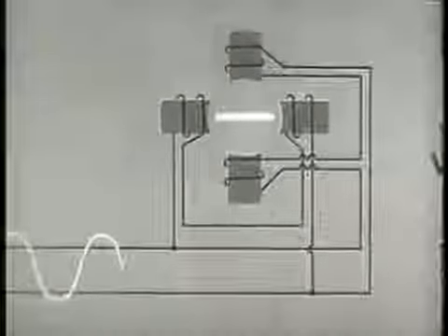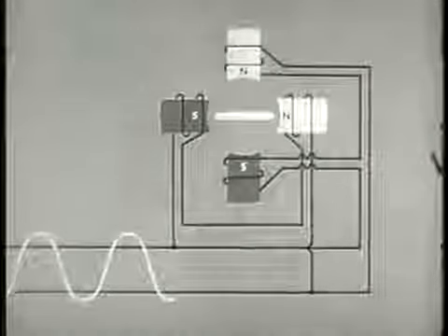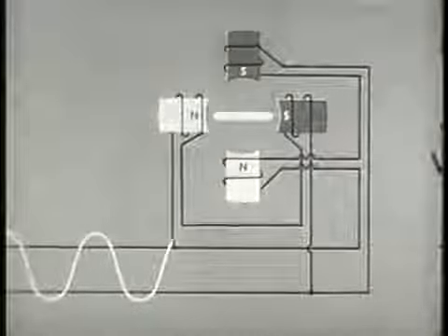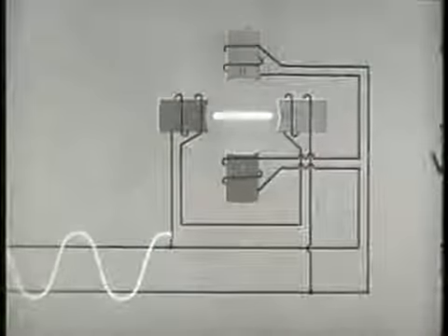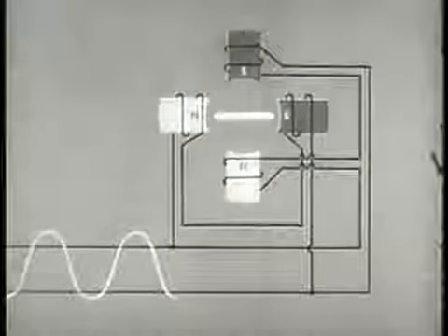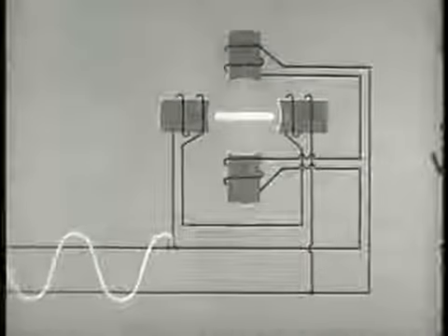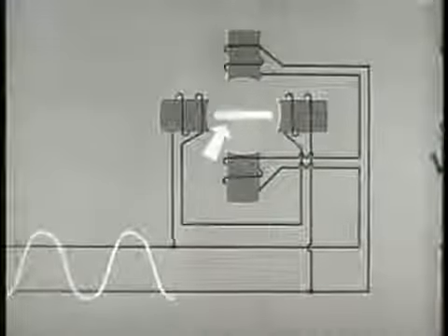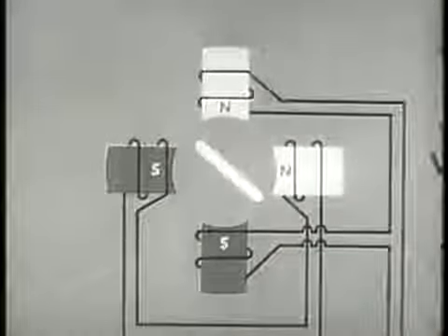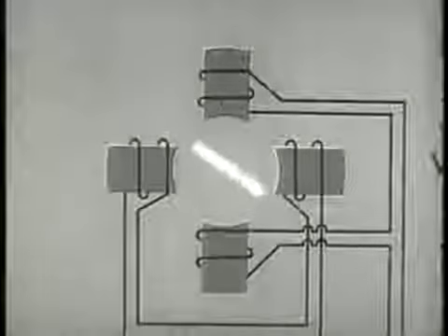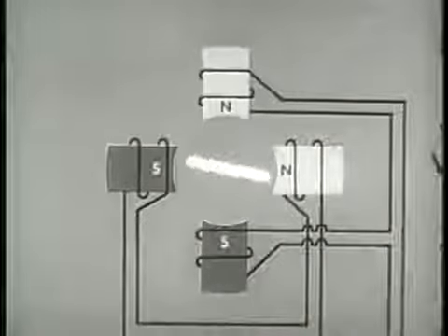In the single-phase induction motor pictured here, the single AC output energizes both sets of poles simultaneously. There is no phase difference in this arrangement, and so the field will not rotate. As the cycle of the AC wave changes, the poles pulsate alternately. But since there is no relative motion, the rotor will not turn. The major problem is getting it started. If the rotor is started by hand, relative motion is created and the motor will continue to run. But this is not a very practical method.